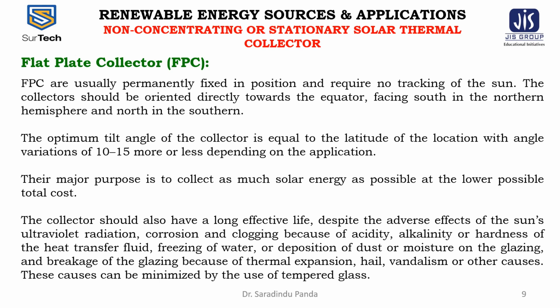Now, the flat plate collectors are usually permanently fixed in position and require no tracking of the sun. The collector should be oriented directly towards the equator, facing south in the northern hemisphere and north in the southern. The optimum tilt angle of the collector is equal to the latitude of the location, with an angle variation of 10 to 15 degrees more or less depending on the applications.